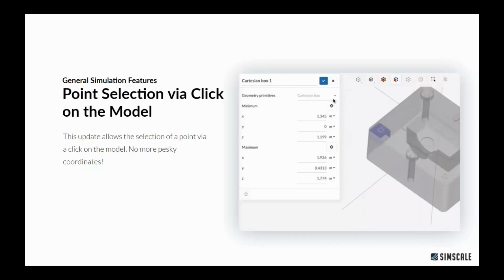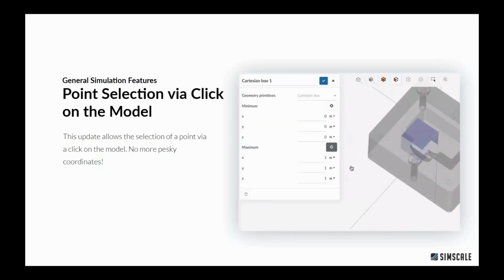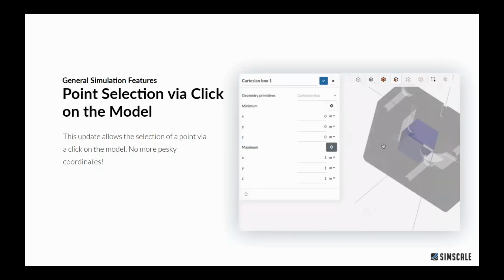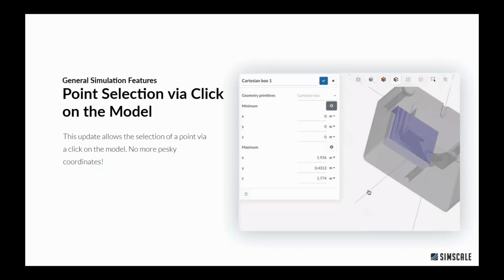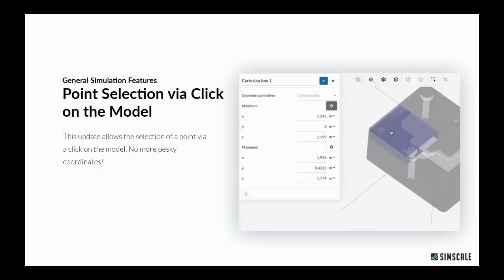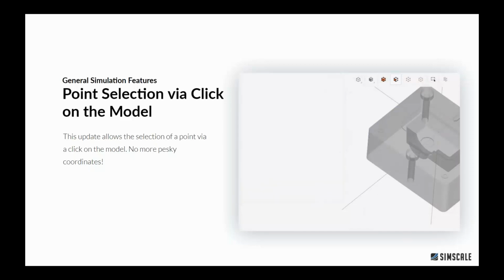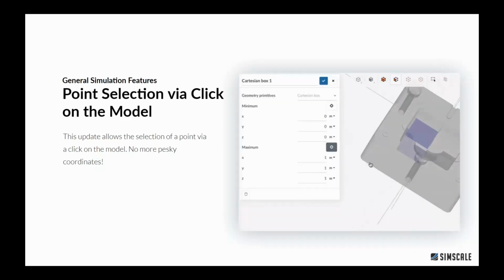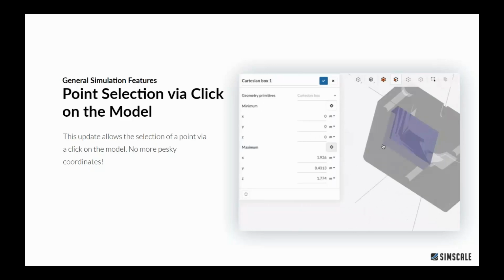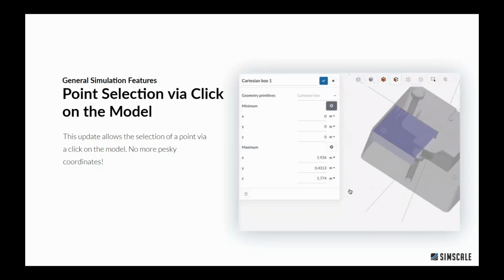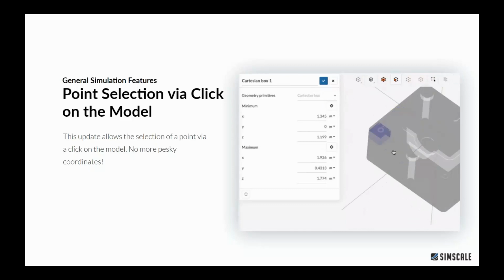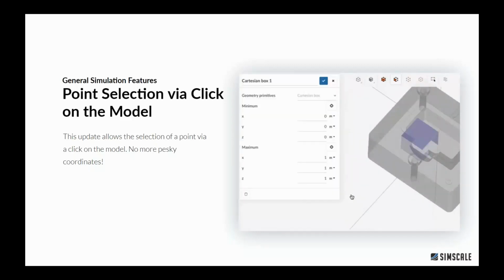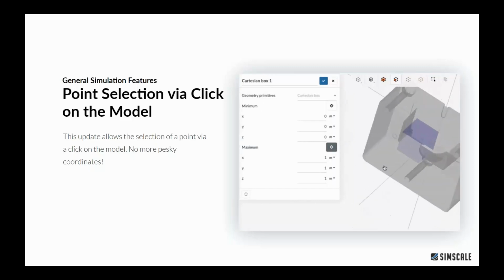If you have a row or a table of different fans, for example, I'm thinking about a data center where you have a lot of different fans, a lot of momentum sources in your model, we can pattern these blocks and space them equally across a certain length. That's really useful, and that is something we are keen on developing, making it a lot more accessible for you to set up the model.